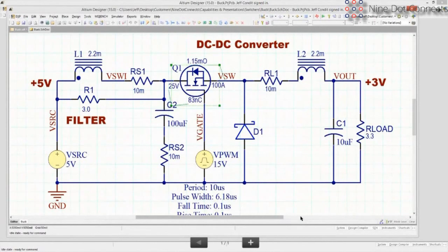The inductors will have their stray capacitances, and the capacitors will have their stray inductances. And the whole LC network of all those stray things will sit there and resonate, and you'll get little spikes and jiggles as a result of it. And that's what you see in the real world most of the time. Okay. I hope that answers the question.